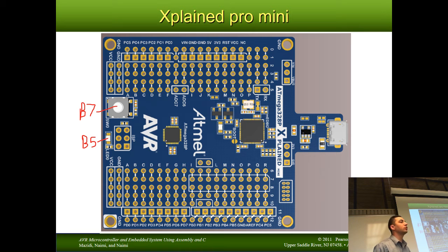If you purchase one of these from the DigiKey link, one of the other pieces that you're going to want to purchase is female headers. It comes without those. And rather than soldering in, we want to be able to use our hookup wire, so we can solder that in. It comes with 2 footprints. One footprint is the Arduino footprint, which I loathe, specifically because of this gap right here. That's not a standard 0.1-inch gap, but the breakout board makes it nice and easy for us.